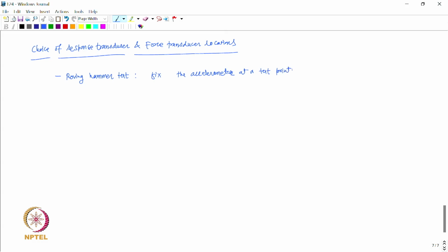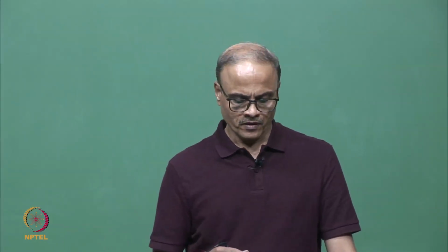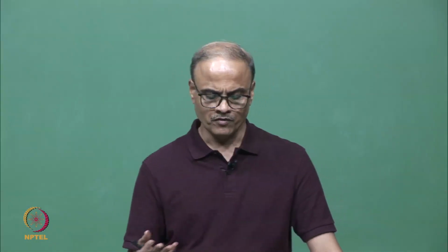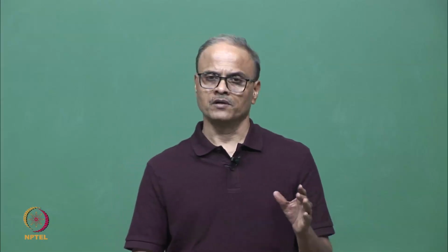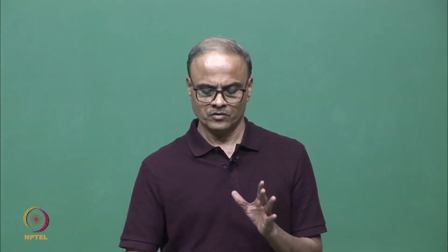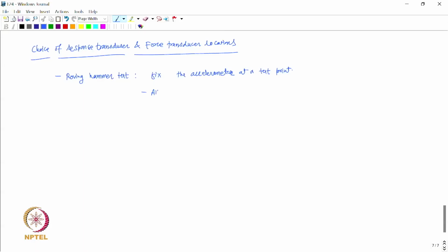That will be permanently mounted at that point and will not be moved or varied when the measurements are taken over different points. The test point where this accelerometer is fixed should be such that all the modes in the frequency range of interest, which we want to measure, are observable from the location of the accelerometer.